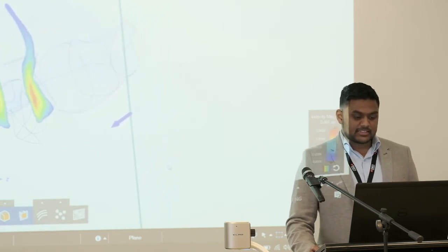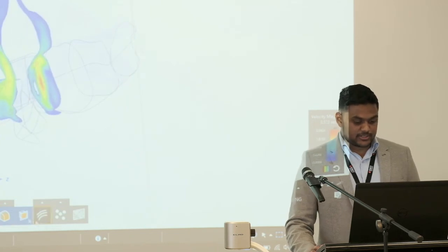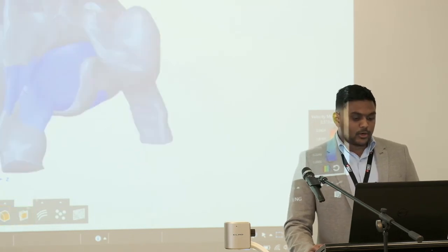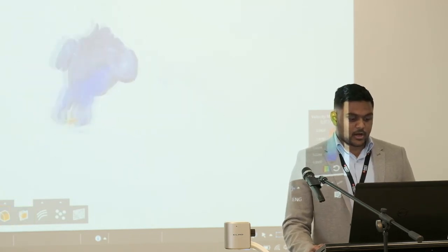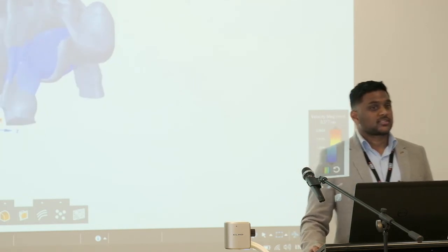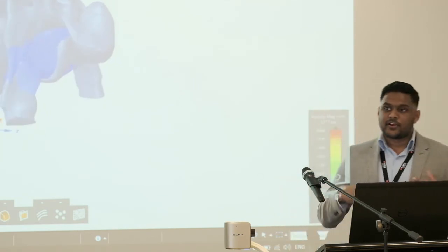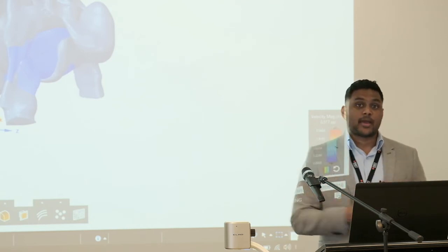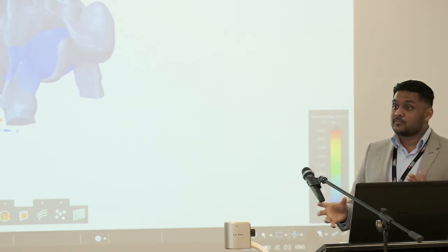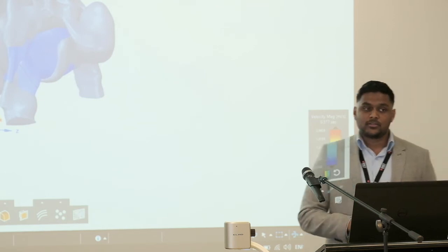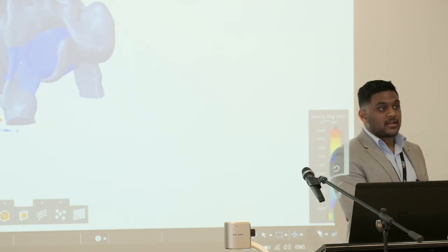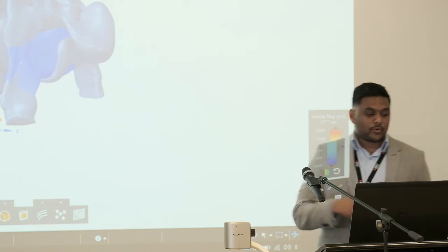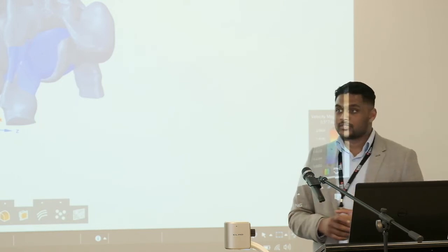I can very clearly see how the flow actually changes around here. So I hope that gives you an understanding of how you can use tools like Discovery Live to communicate some very complicated information to someone that may not be as technical. We can make some changes, and maybe the engineers can experiment with different changes that can be made to the model and then go away and do their in-depth analysis in Fluent later on. Or we can run through some kind of parametric modeling as well.